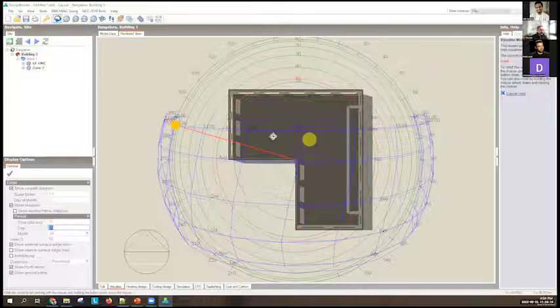So how do you size it? If you size on an average, then when you need cooling here, you're not going to get enough, but you might make the internal zone too cold. So everybody's uncomfortable all of the time. So to avoid that, we have this concept called perimeter and internal zones. But when you divide the zones, there is no physical partition. So we use a virtual partition to do that.